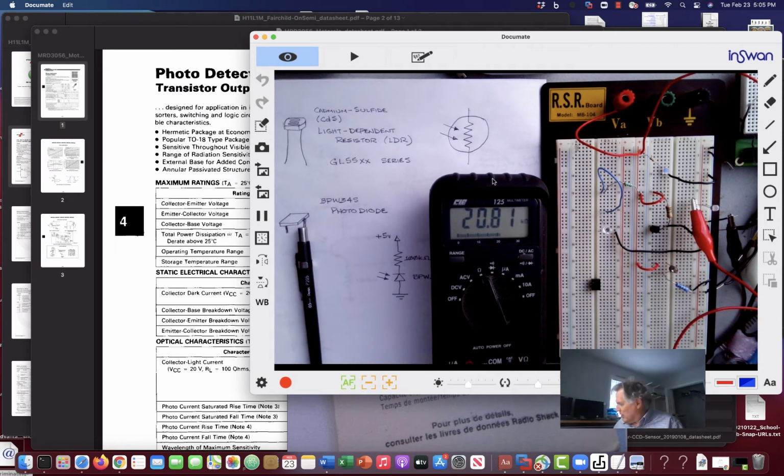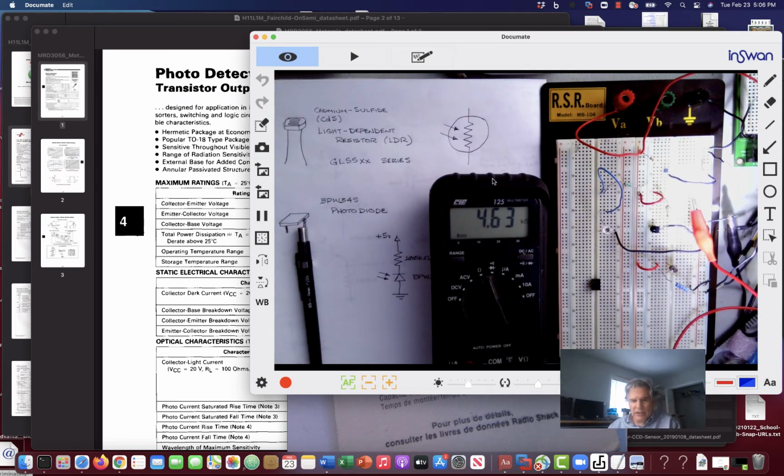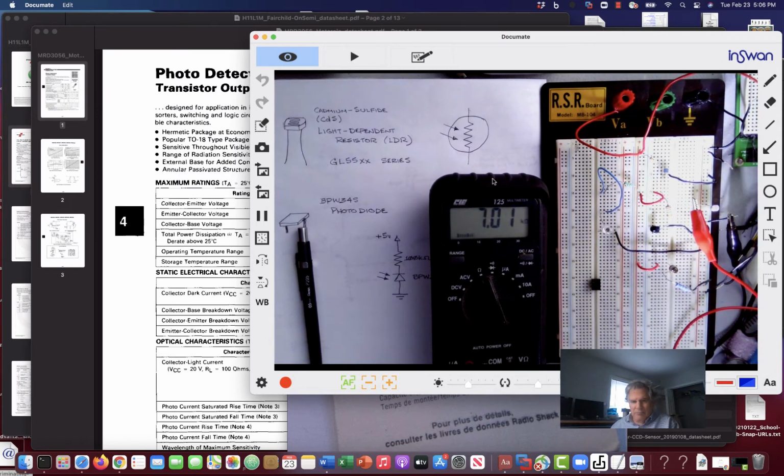Then we'll take a flashlight and we'll shine it on that device like so, and it drops down to 3 k ohms, or even less, and as we pull away and shine the light from a different angle so that it's not as intense, you can see that the resistance goes up the less light that falls directly on the sensor.